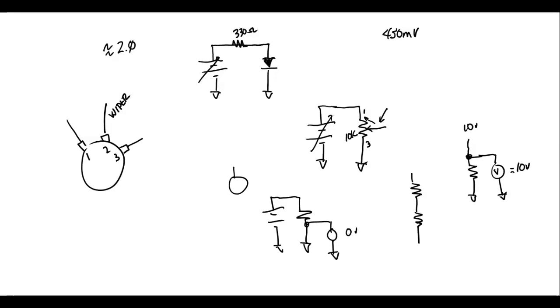Well, if I put it away from the top, if we move it all the way to the top, we get whatever voltage we put across it. If I move it all the way down to the bottom, I get a 0. If I move it somewhere in between, we get a two resistor voltage divider.